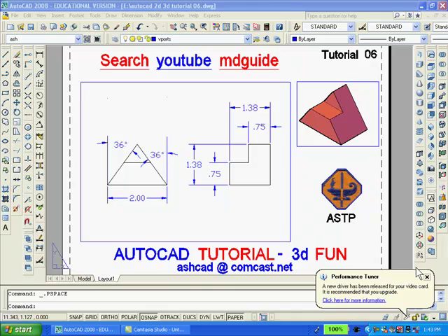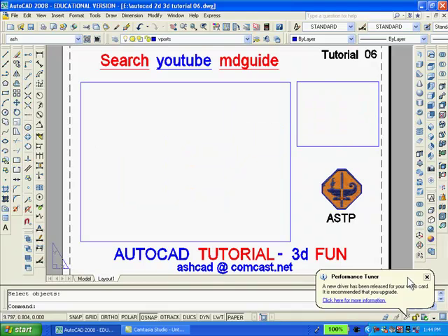The first thing to do is to erase both the large and small viewports. You can see that the drawings disappear from Paperspace. All that remains are two rectangles which I drew previously to serve as templates for when I redraw the viewports later on.